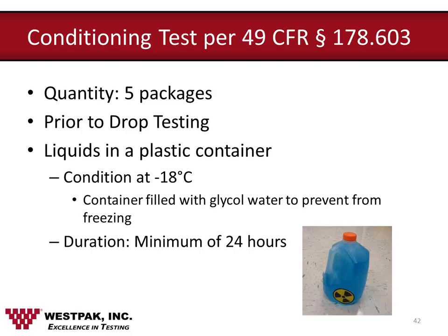Will these closures just pop off? Will these bottles actually just crack? The only way that you know is that you subject them to freezing temperatures for 24 hours and then you drop them right afterwards. But just remember that when we're actually conditioning them, the water inside is not water, it's glycol water or antifreeze, just to prevent them from freezing.